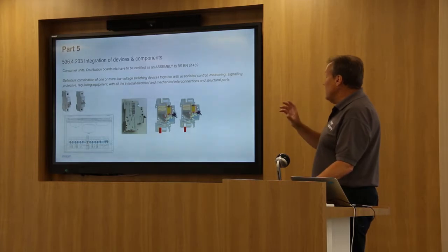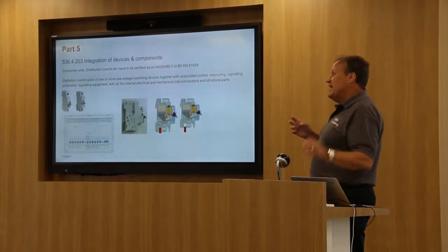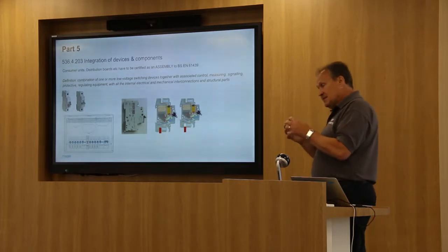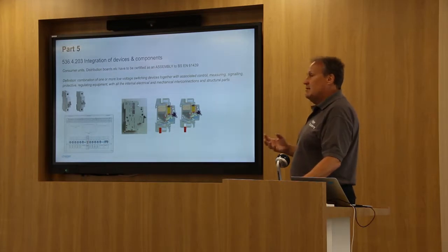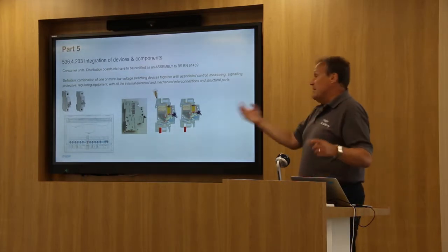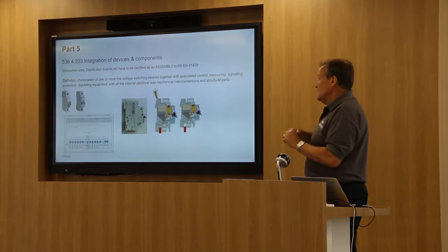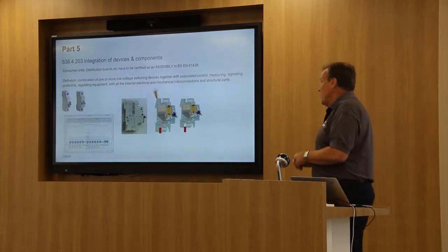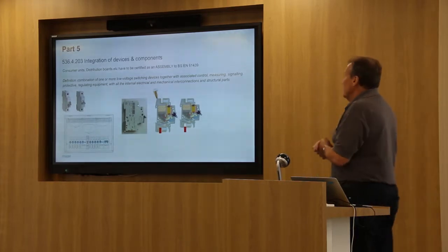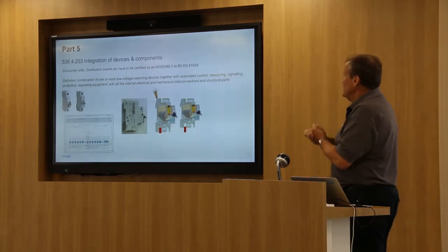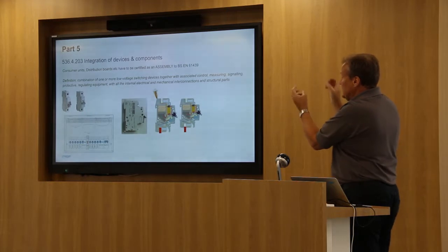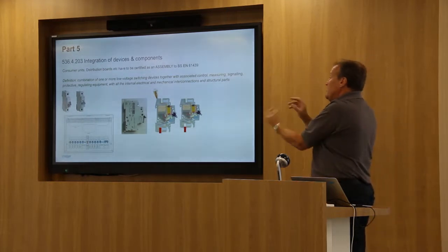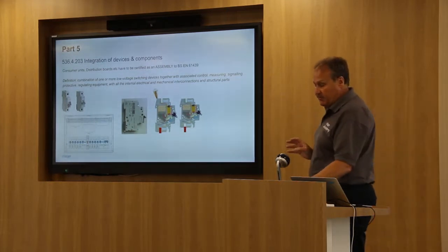Also, the internal components do not have to be in the same direction. If you get a fault, there's a lot of energy inside this device as it dissipates the arc generated by this fault. Some superheated gases are produced inside, which have to come out. So there's always a very small vent hole in circuit breakers to exhaust this gas. For our product there, it exhausts the gas up top, above the MCB, into a nice open space above the circuit breaker.